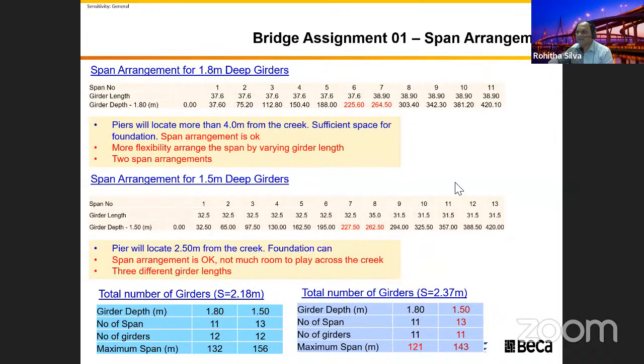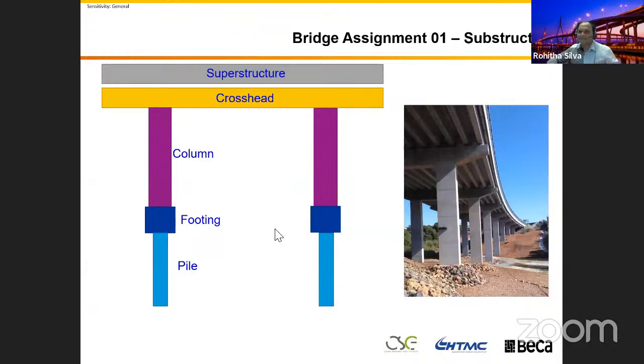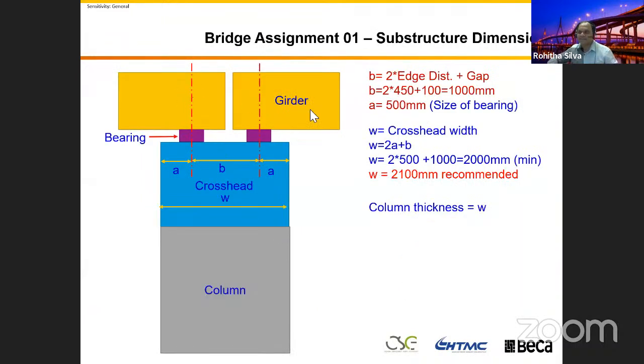So then we place the two girders aside. When you place the girder, it's heavy, right? Sitting on the bearing, there is a significantly large pressure in here. If you do not have a sufficient distance in here, this concrete will crack. And if a bearing is warped, the bridge will slip. During an earthquake and other conditions, there should be a space. If a bridge slips, it should not come down. So there are so many reasons for that, and the size of the bearing itself, they are not small.